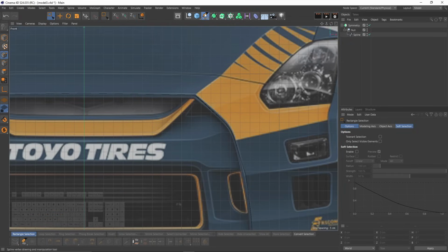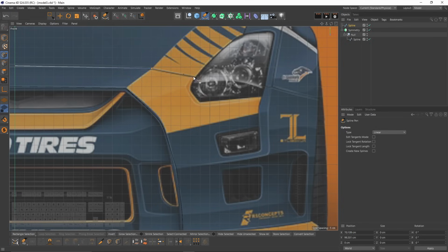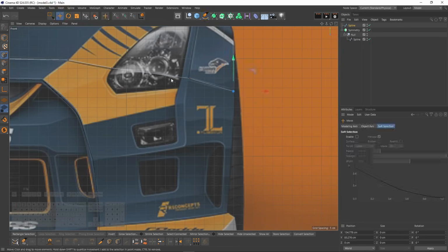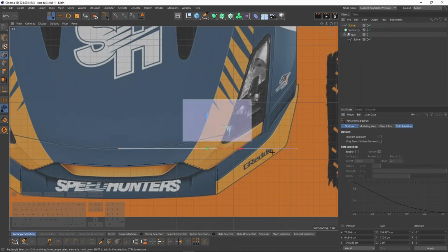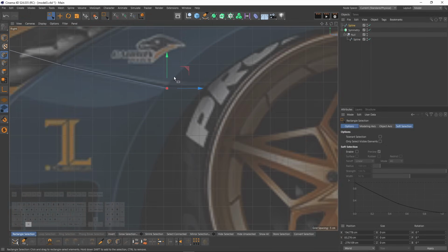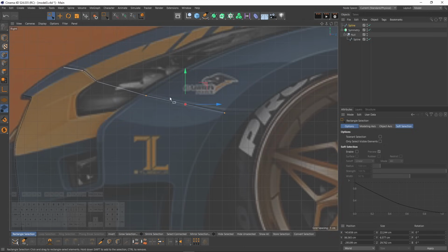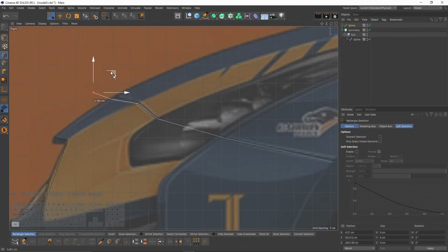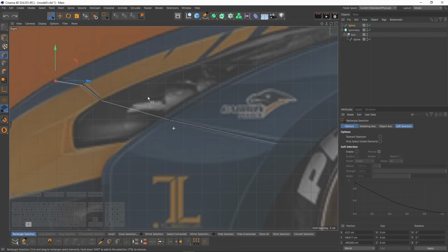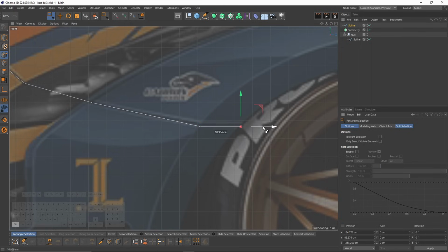Then let's create that spline. Go to top view. Let's switch back to right view. This time I want to extrude that point. So the first thing I need to do is reverse this point's order, because I can extrude the white point just like that, by pressing Ctrl. To do that, let's select this last point, point order, and reverse sequence. Now I'm gonna press Ctrl and extrude that point.